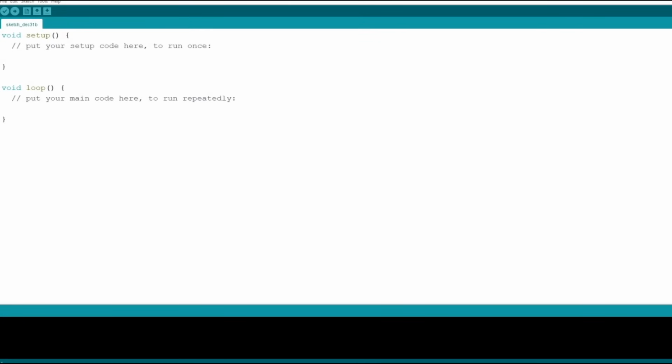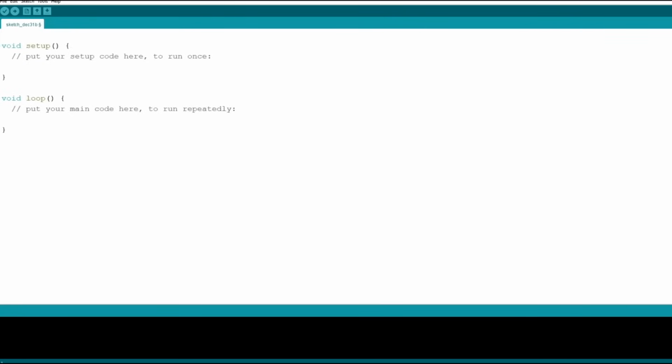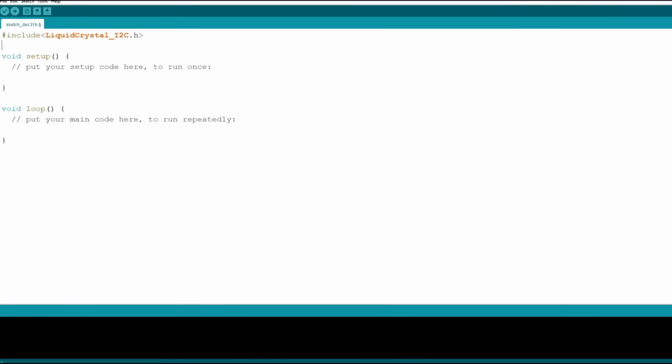First of all, let's include our LCD screen library. So let's move to the top, and let's include our LiquidCrystal_I2C.h library. And then let's move to a new line, call our LiquidCrystal_I2C class.